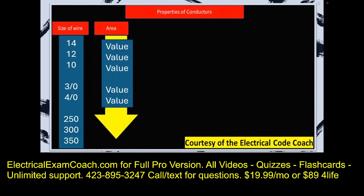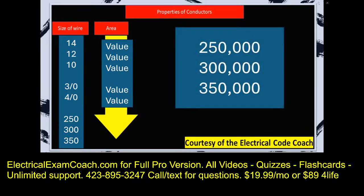And the reason is because the left-hand side of this table, the 250, 300, and 350, are already showing you what the circular mils are in kcmils. So we have 250,000, 300,000, 350,000. So once you get past 4/0, you're going to get into 250, 300, 350, and all you have to do is add on the 3 zeros.